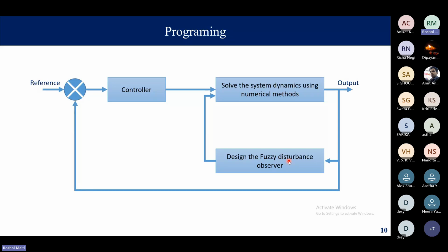Here for the twin rotor MIMO system, we will have 6 states. Therefore, from x1 to x6, we will have different values a1, b1, c1 like this, and different rules we have to formulate for fuzzy, and ultimately we have to calculate the membership value, the percentage of membership value of each input which may stay in that region.